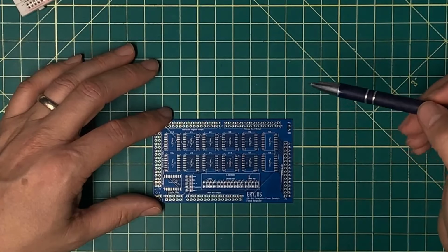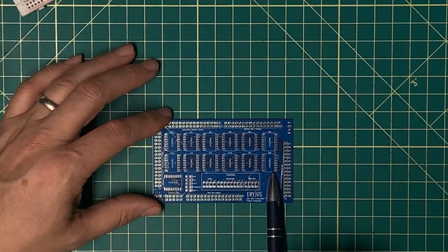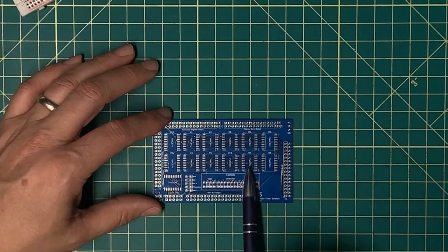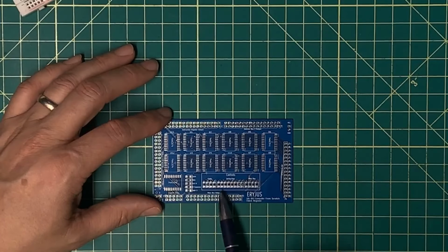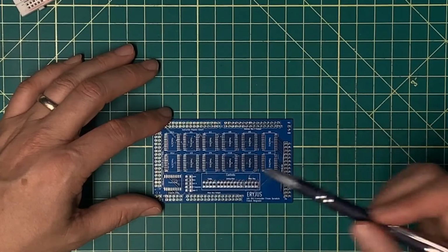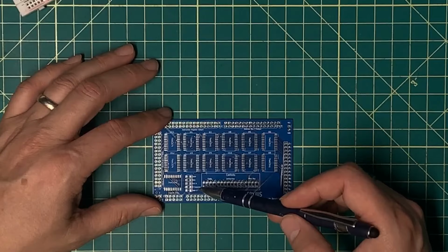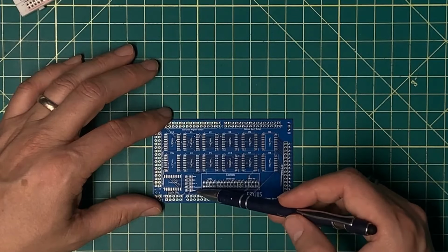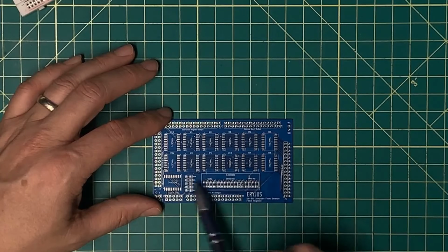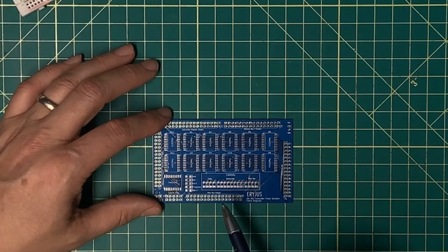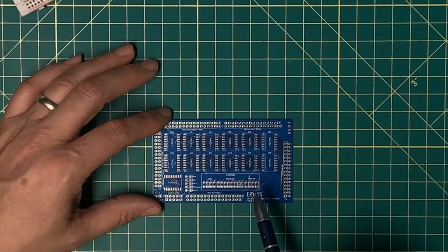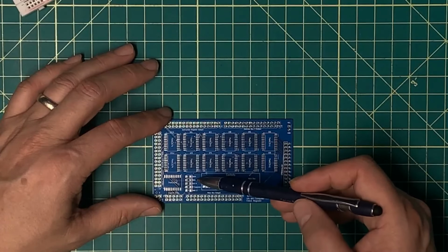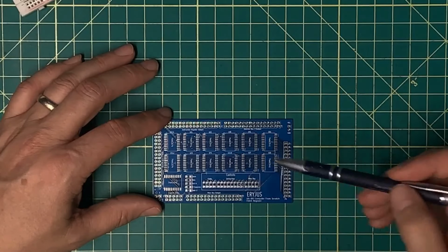In the general purpose register design, I've changed that so that I eliminate the line drivers as extra ICs and instead latch each individual place that the data can go. The signals here are passed from the control logic, or used to be passed from the control logic, in the native format that the particular module expected. Since each of these asserts were active low signals, each of these signals came in as active low and then they were directly sent off to the individual ICs. In the general purpose register in my current build, I am passing these all off as active high signals, and these would need to be inverted if they were required on this particular module. So in other words, the main bus assert is an active high signal coming from the control logic, but because the assert control lines are active low, I would need to pass that through an inverter.